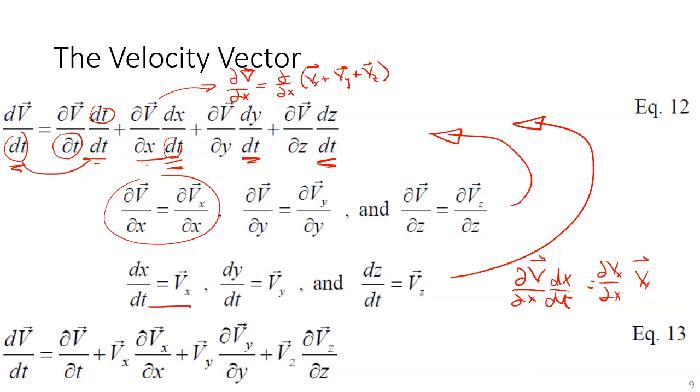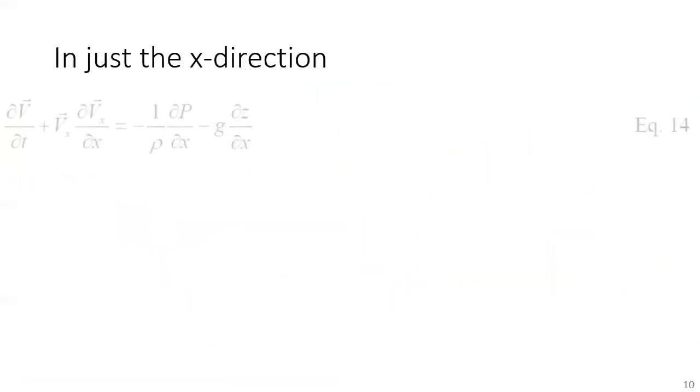If you have unsteady flow, think of a dam break. You're fishing by the side of the river. You're at one location, and what you see is this big flood wave coming downstream. The water surface rises up because the discharge is changing, and therefore the velocity is changing. So local acceleration, convective acceleration. And that's what the total time derivative of the velocity vector is. It has these two components.